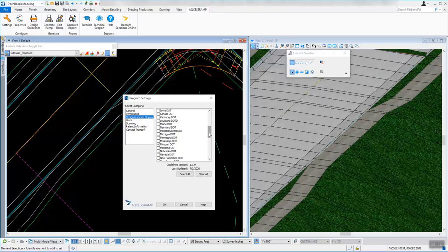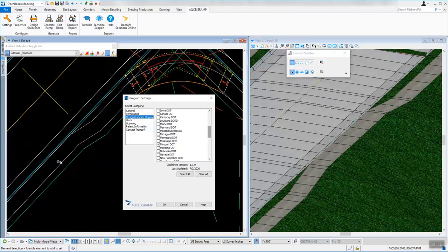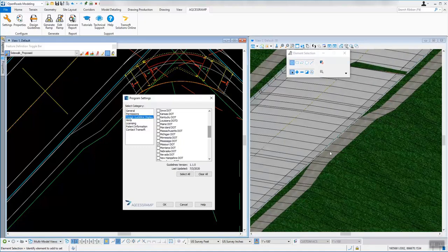So overall, the tool is designed to create all the line work and even a surface for an ADA compliant sidewalk or curb ramp in different locations. You can see I have one drawn back here already. The one I'm going to show you deals with this location right here, where I want to have an ADA ramp that might go across a curbed roadway.